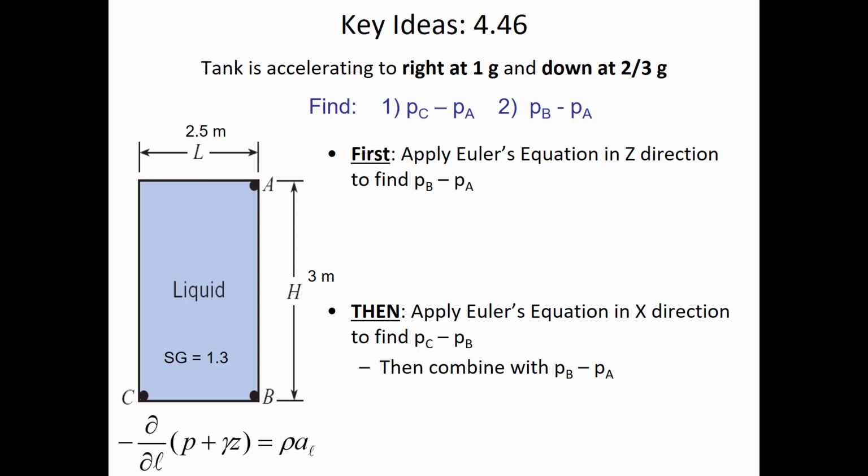So you have that qualitative expectation that when you're crunching the numbers, you find a pressure increase where pressure C is bigger than B. So the equation itself has some places where, for example, Z's are going to be relative to some elevation datum. And then also the acceleration has a direction component to it. So it's important for us to not use 2 and 1 interchangeably in Euler's equation. Great questions. You got another one?